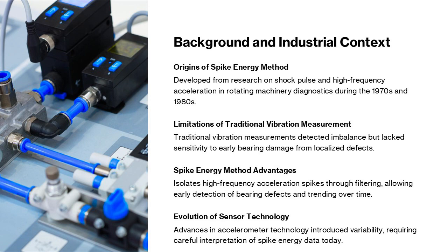bearing damage. Engineers observed that localized bearing defects produced repetitive impact forces, exciting the natural frequencies of the bearing and surrounding structure. These impacts manifested as sharp, high-frequency acceleration spikes. The spike energy method was designed to isolate and quantify these events by applying high-pass filtering and specialized signal processing.